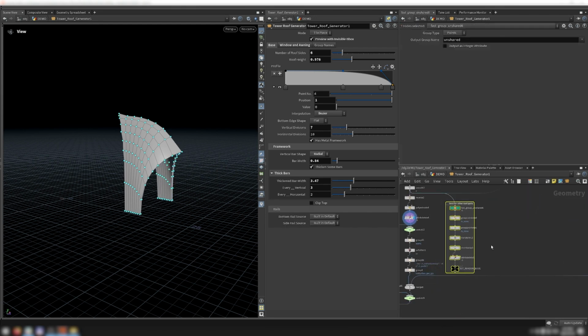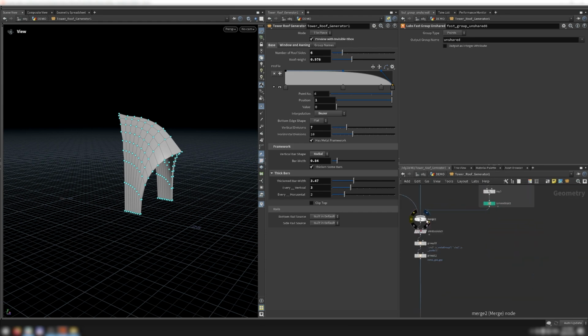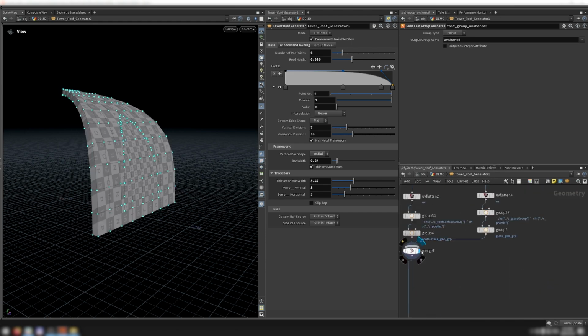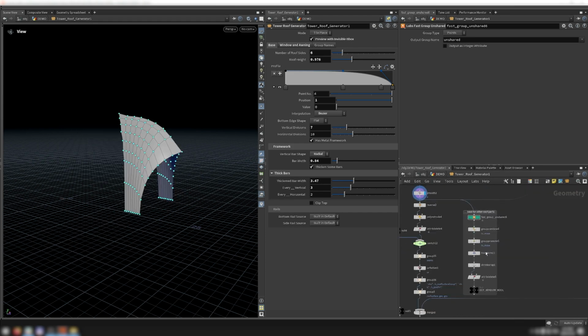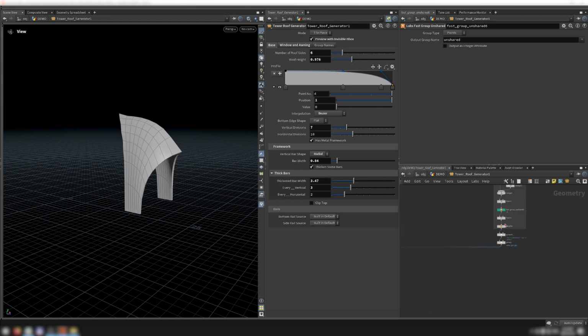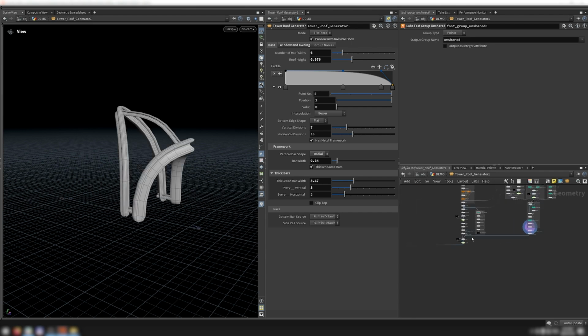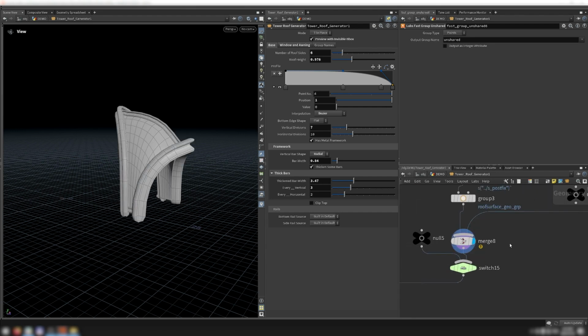Here is where I create the mesh that gets booleaned out of the metal framework and the roof surface. I just take the awning surface, I stretch it out to make sure it'll intersect with the necessary geometry, and then I shrink wrap it so it's manifold. Lastly, I create the rails for the awning so those can be merged together with the awning surface.